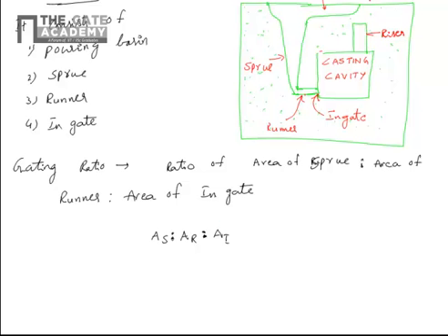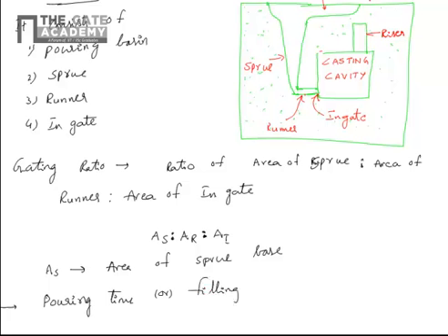So area of bottom sprue, area of sprue base, not on the top. Top is high area, right? At the sprue base, you need to take less area. It helps us to know the discharge, how much is the maximum discharge. Okay, next is pouring time or filling time.